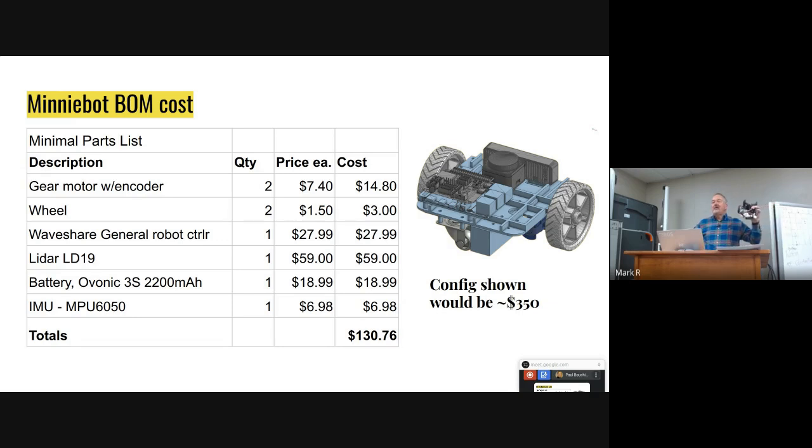And so the way you go cheap, if you just want to play with it on a ROS robot, is you run ROS on your laptop, which I'm doing here, and you have the microcontroller Wi-Fi connected up to ROS on your laptop, and the micro ROS interface supports either serial or Wi-Fi. I've done it both ways.